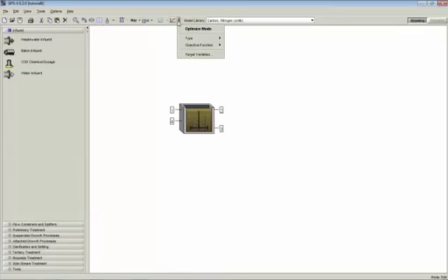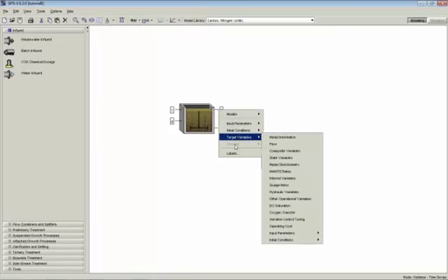Just to quickly show you how that would be set up, if we go here, this is the optimize button, by the way. If we go down, we can pick the different types of optimizers that we can do. We can take a look at the different forms of the objective function, but the most important thing to set up at the beginning is your target variables. So I turn optimizer mode on, and in this case, we are trying to fit the soluble substrate concentration.